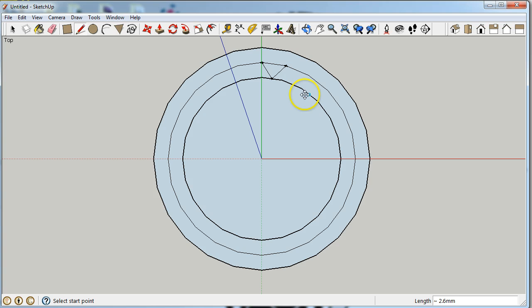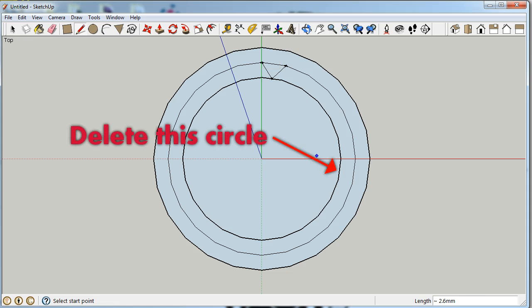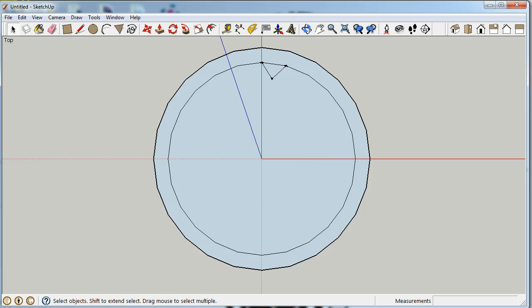Then we are going to be duplicating that triangle in what we call an array function, going all the way around the origin, revolving around the origin at 360 degrees. So in order to complete the array feature, I'm going to select, holding the shift key down so that you see the plus and the minus sign, both of these lines that create the corner of the triangle that will be duplicated. Once I've selected both, I'm ready to rotate and duplicate those copies.